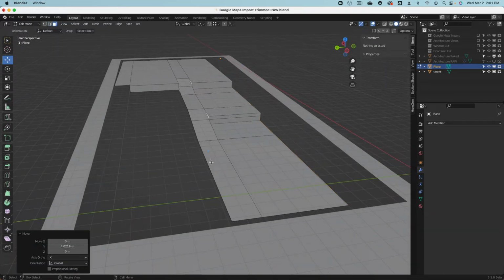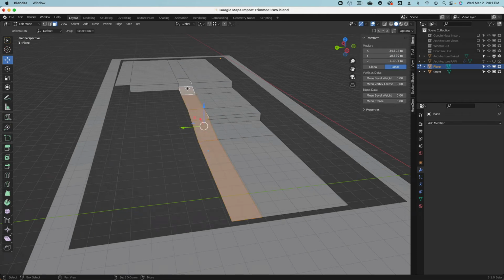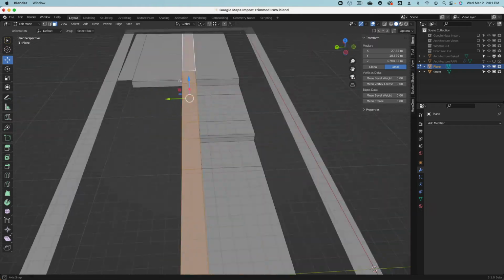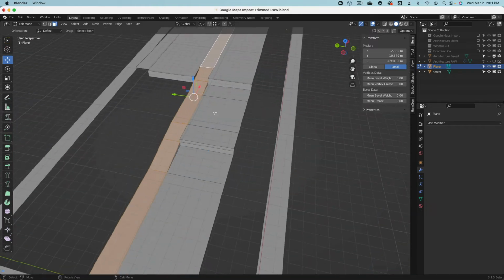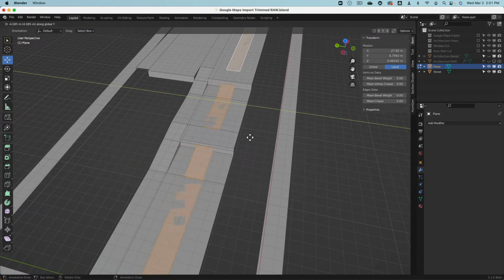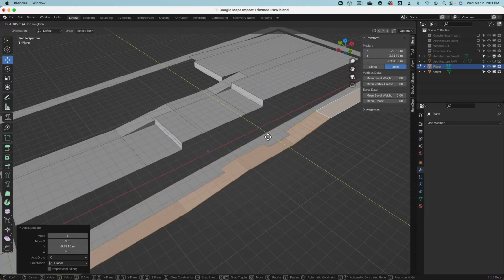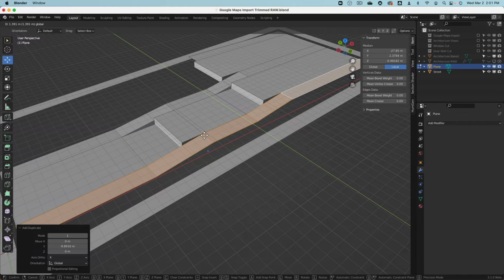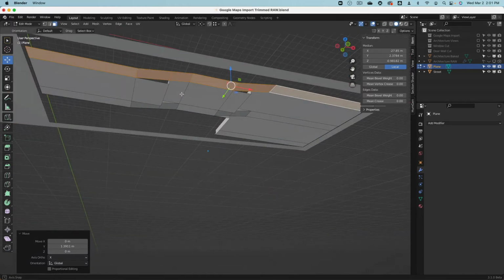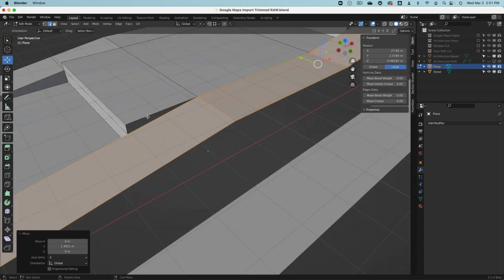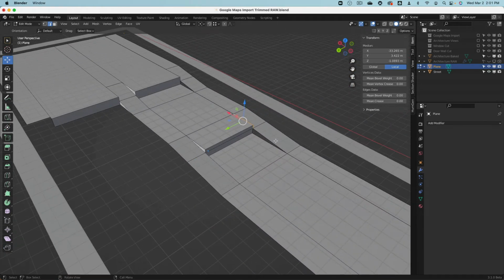And then I go into face select these faces. Yeah. Shift D and Y. So I slide them over on Y. Go back to here, hold Control, snap them to there. And then, well, just fill in the missing faces.